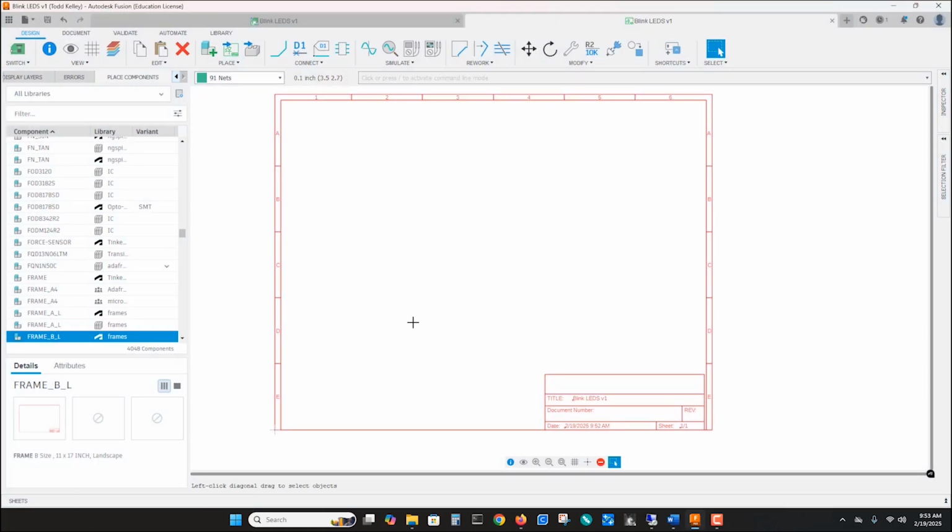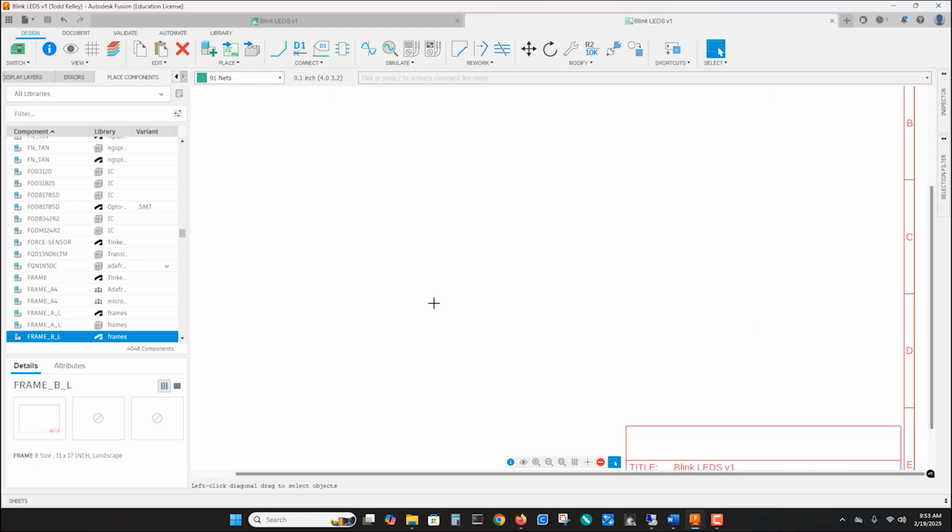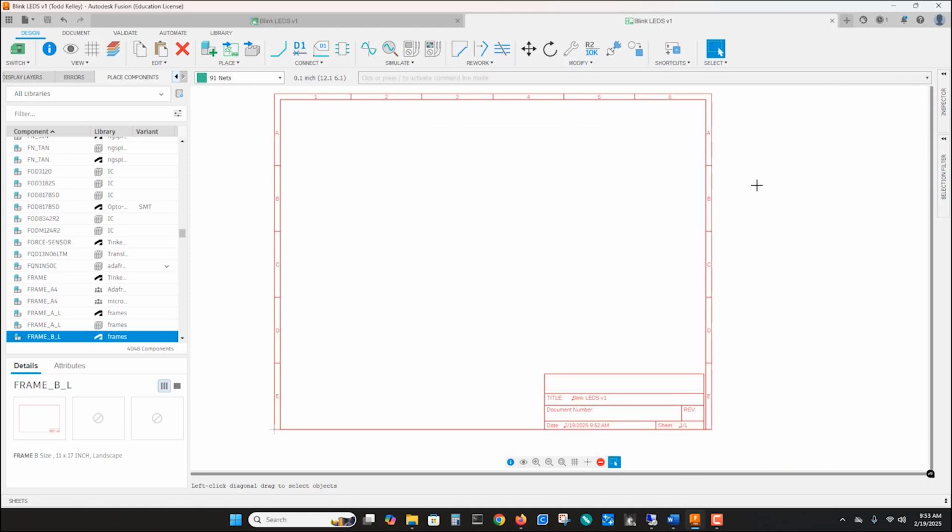Notice the scroll wheel controls the zoom function. And if you're in Fusion, you're definitely going to want to use your scroll wheel. By default, it is reversed from most other software zoom functions. Let's fix that real quick. Click on your profile at the top right corner and select Preferences.